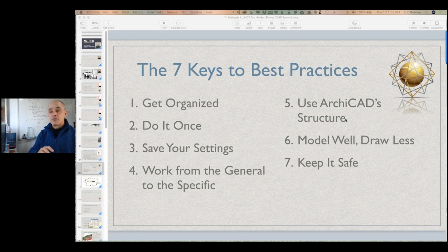I've seen people, for example, say save view and place on layout. That's a nice convenient way to quickly get whatever you're looking at onto a sheet, but it may just have a generic name like first floor, and you might have 5 or 10 or more that say first floor. And then on the sheets, you have the title. Well, if you go back or think ahead and make that view have a name, like first floor reflected ceiling plan or site plan, etc., then these will actually flow forward in ARCHICAD structure from the view name to the drawing name. So if you change it once in the right place, it flows down.